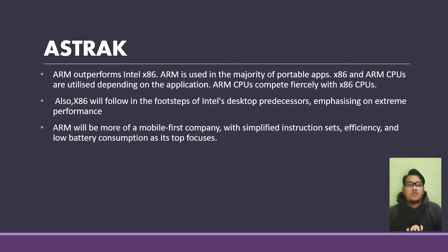So our empirical investigation demonstrates the role of ISA in modern microprocessor performance and energy efficiency. We find that ARM and x86 processors are simply engineering design points optimized for different levels of performance, and there is nothing fundamentally more energy efficient in one ISA class over the other.